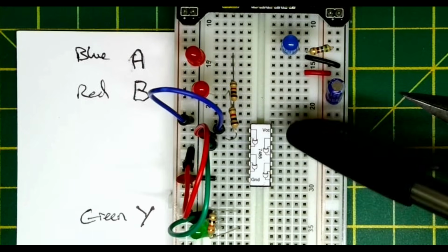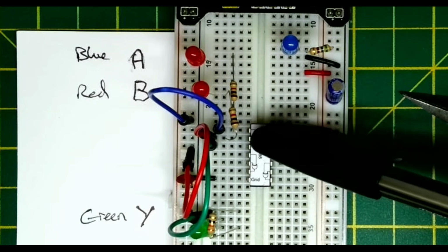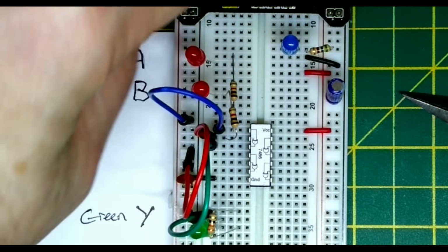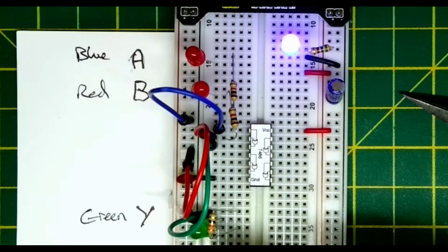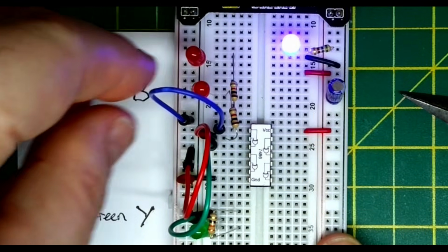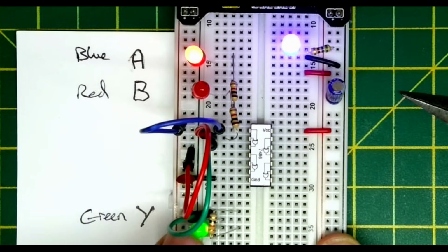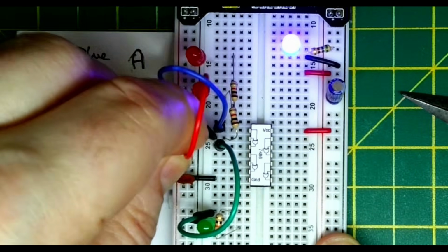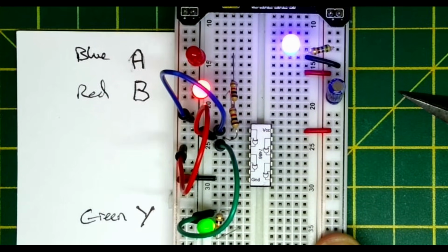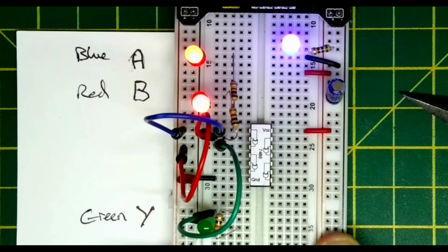Now we have the exclusive OR gate. It's difficult to see, but you can see that this is an OR symbol with an extra line on the inputs of A and B. So we switch this on. You can see the power's on, but we don't have anything output. So the inputs A and B are both 0. If you now make A 1, you can see we have A is 1, and we also get an output on Y. We make B 1, and we also get an output. And if we make both A and B 1, then in fact we don't get an output. So if we go back and have a look at the slide.